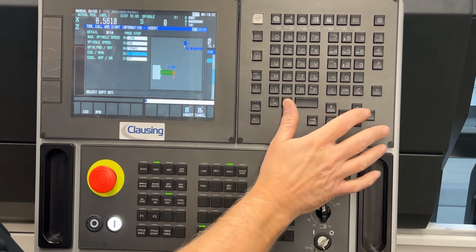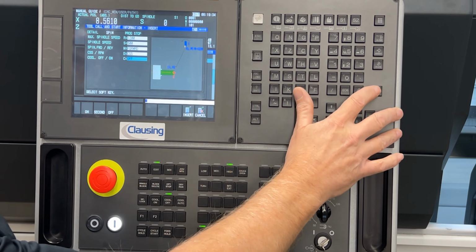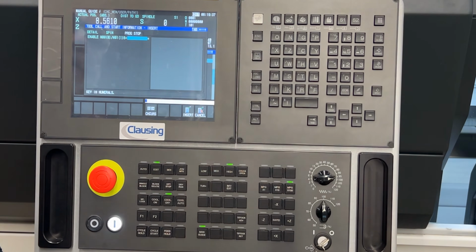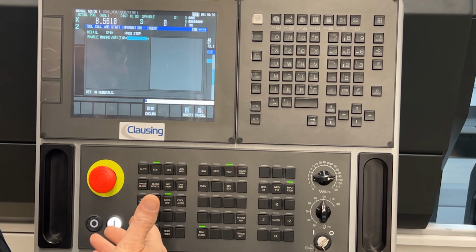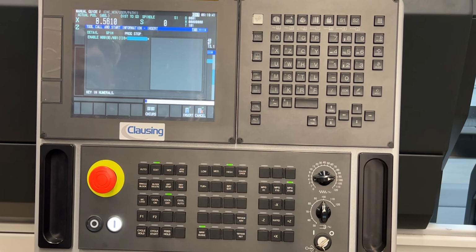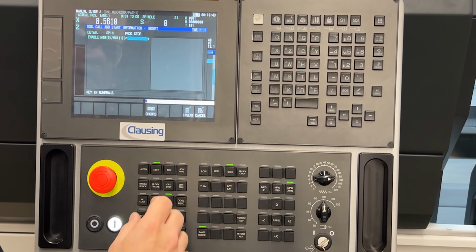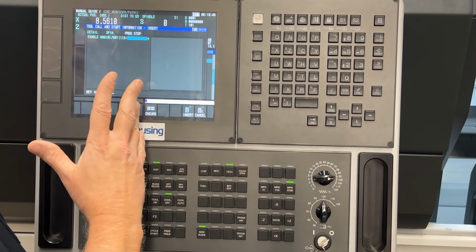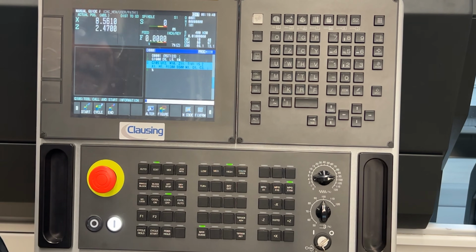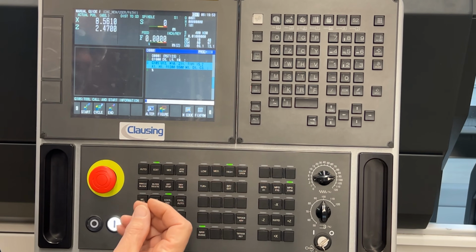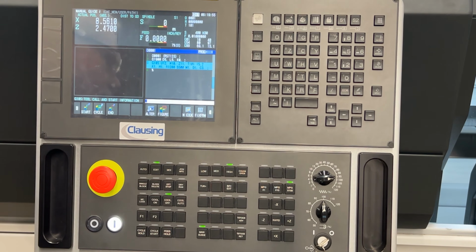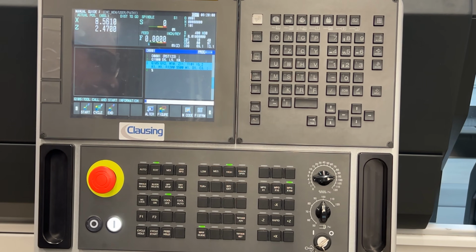And then a selection of coolant on or off. The next page of information is if I want to add in an M0 or M1 in that tool change call out. Once I get it done, then I press insert, and that'll be my tool call within the part program. Again, this was created by Colchester Harrison, and it's implemented in the XS machines. Most other machines will not have something like this in it.